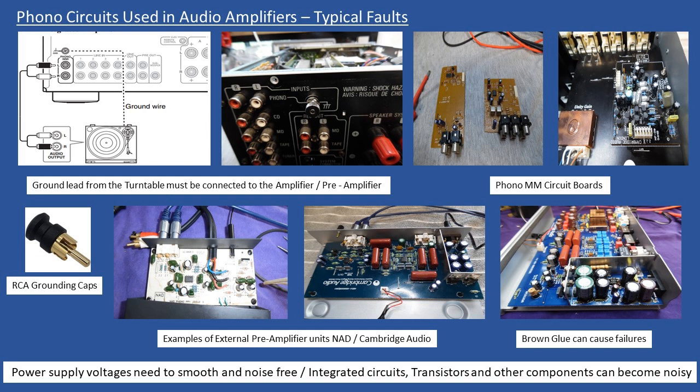And then after voltage regulation, it's not uncommon to see additional filtering. So you could have yet again some high frequency 100 nanofarad capacitors connected on the output of the voltage regulator circuit to eliminate noise. And that's very, very important.